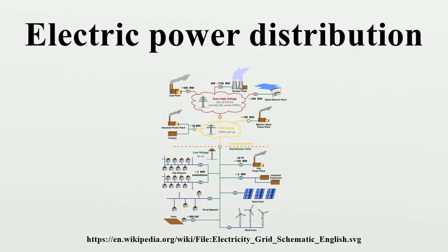A ground connection to local earth is normally provided for the customer's system as well as for the equipment owned by the utility. The purpose of connecting the customer's system to ground is to limit the voltage that may develop if high-voltage conductors fall down onto lower-voltage conductors, which are usually mounted lower to the ground, or if a failure occurs within a distribution transformer. If all conductive objects are bonded to the same earth grounding system, the risk of electric shock is minimized.